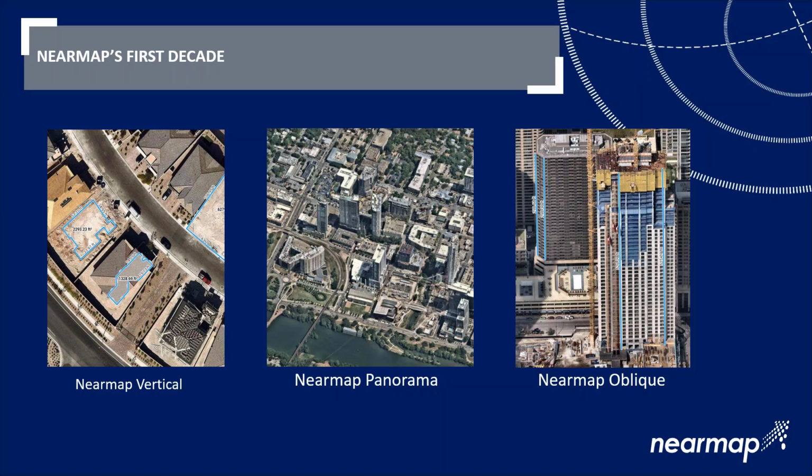You're able to do that because our camera system actually sits on the bottom of the aircraft and rotates from 0 to 45 degrees, capturing about 40 to 60 different images that are overlapped on top of each other on every point on the ground that we collect. And those are all ortho-rectified using ground control points into a seamless mosaic that's then hosted in the cloud to be consumed within just a couple weeks of capture.